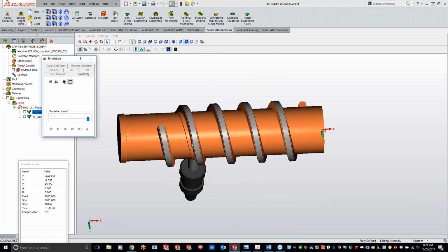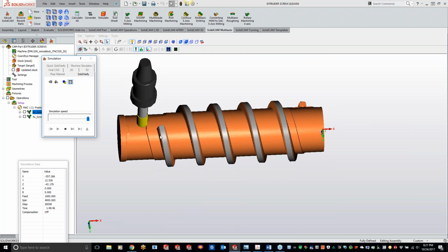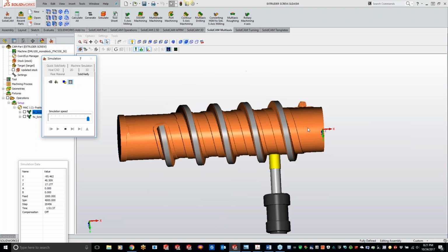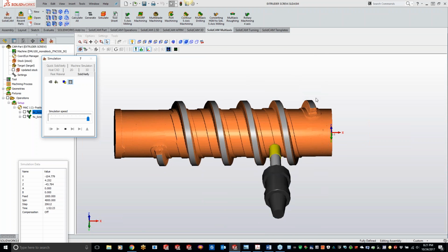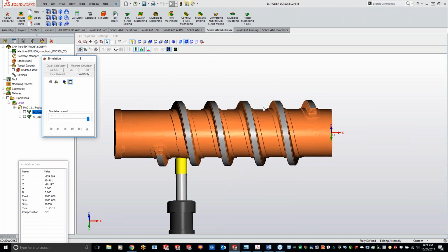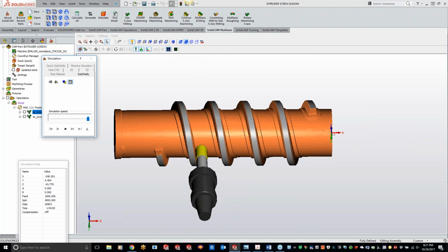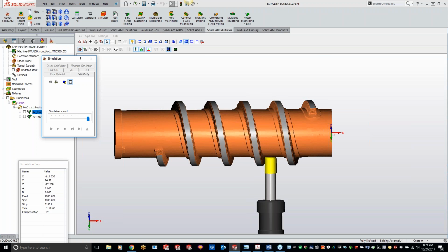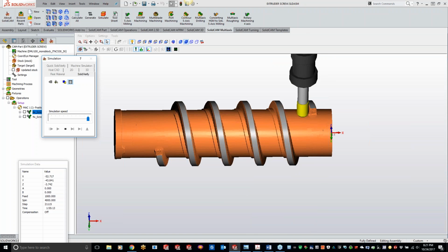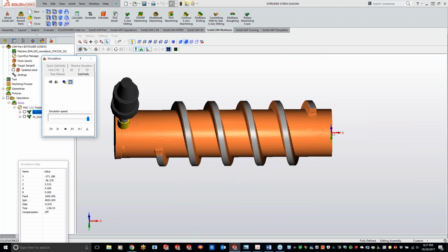In the tool path, we're not getting a lot of jumping around, and what it's doing is getting everything roughed out. But once it's in contact with that screw edge, I guess you would say, it stays in contact, and you kind of see where it loops around up here and just goes back and forth, working your way through. So it works like a 3-axis roughing. However, the main slicing is performed in a cylinder space and not just one direction. So it's just constantly going back and forth.